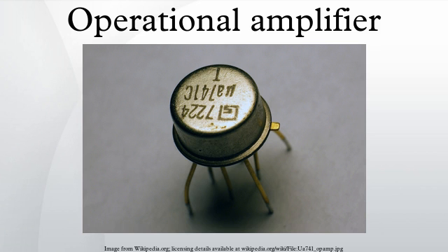1953, a commercially available op-amp. In 1953, vacuum tube op-amps became commercially available with the release of the Model K2-W from George A. Philbrick Researches, Incorporated. The designation on the devices shown, GAP/R, is an acronym for the complete company name. 2 9-pin 12AX7 vacuum tubes were mounted in an octal package, and a Model K2-P chopper add-on was available that would effectively use up the non-inverting input.